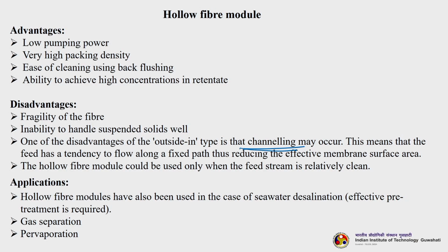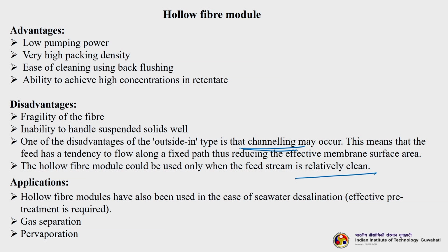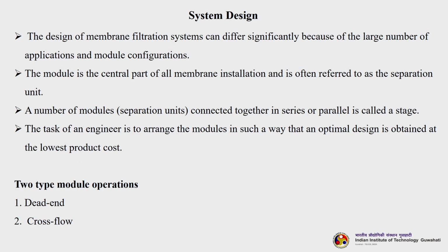The hollow fiber module could be used only when the feed stream is relatively clean. That means it is clearly understood that it cannot handle suspended solids. Applications are seawater desalination, which is effective, but still some effective pretreatment is also required, gas separation and pervaporation.